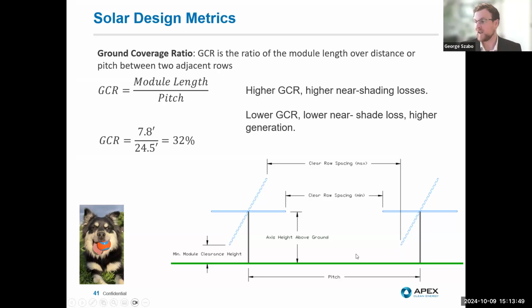Right. Well, again, if your racks are spaced out further, it's going to be better for generation. Similarly, if your racks are elevated, that's also better for generation. But it does require additional steel length because as much as you add above ground, you also have to add below ground, if not more, to counteract your moment of rotation or the point at which the entire thing is just going to bend over.